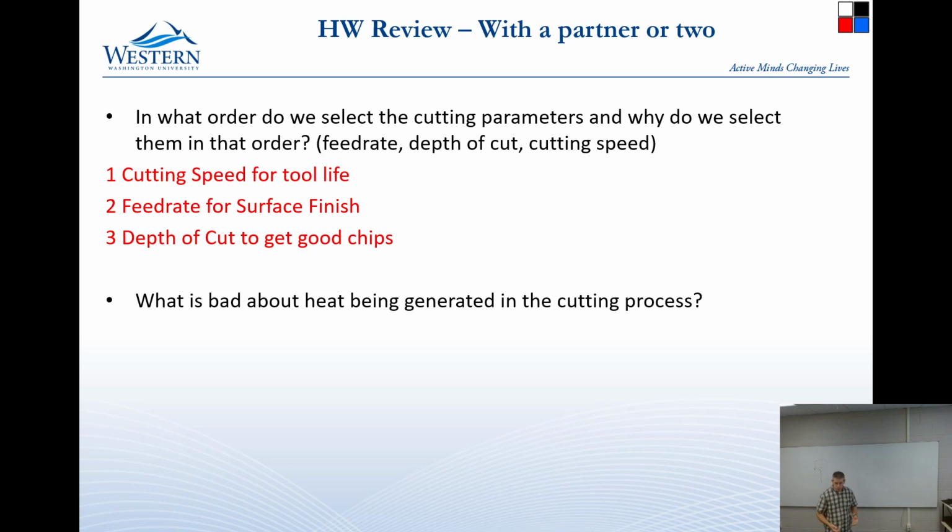So if it was a rolled part, or just whatever happened last, it may have a lot of residual stress locked in it. But it would be pretty rare to be able to put enough heat in a part to warp it in a machining process. It would have to be very, very thin.